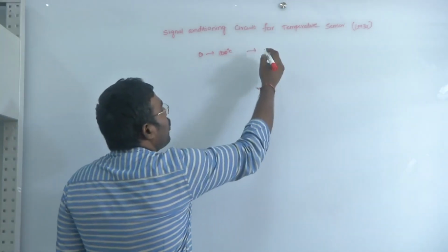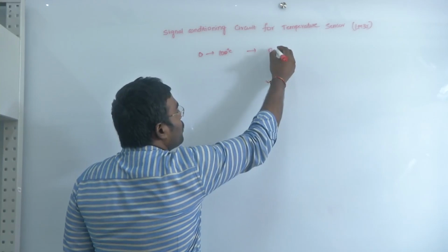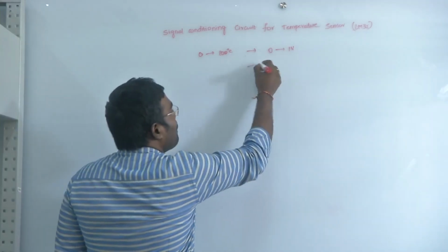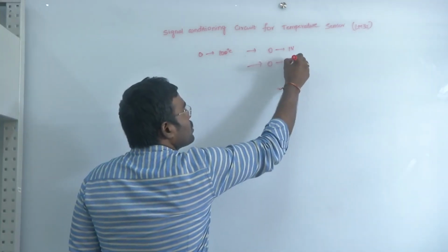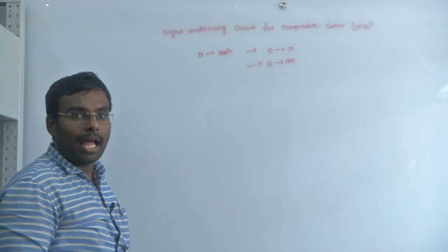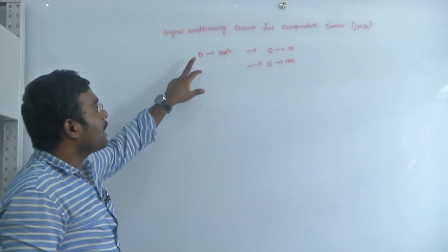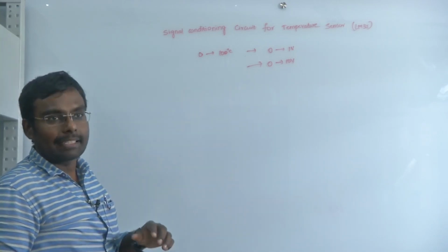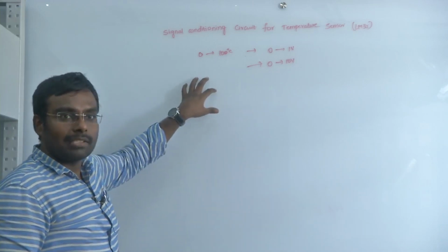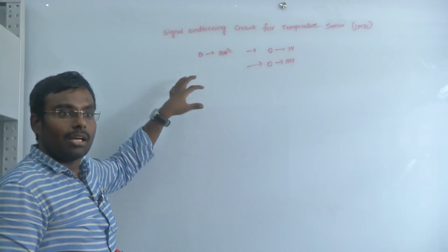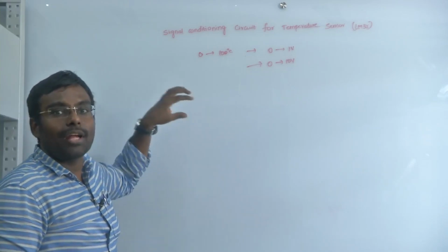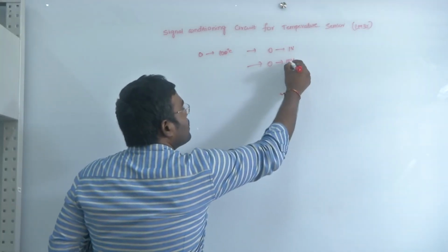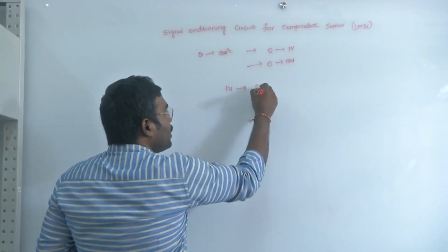Generally we get an output of 0 millivolt to 1 volt, but if we can implement 0 to 10 volts, then the resolution of the system will be higher. The minimum change that it can record is 0.39 degree centigrade, provided our temperature sensor changes or provides an output signal for a change of 0.39 degree centigrade. Okay. Now, that means I should convert 1 volt into 10 volts.